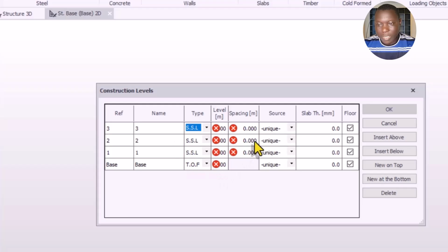All right. So for the height of the story, which is the space in meters, you see in meters M. So for the first story, it's going to be 3.5 meters. For the second story is going to be 3 meters, and then for the third is also 3 meters, just like this. Okay, if you want story 2 and 1 to be the same or to be similar, you need to use this provision. Click here and then select this.